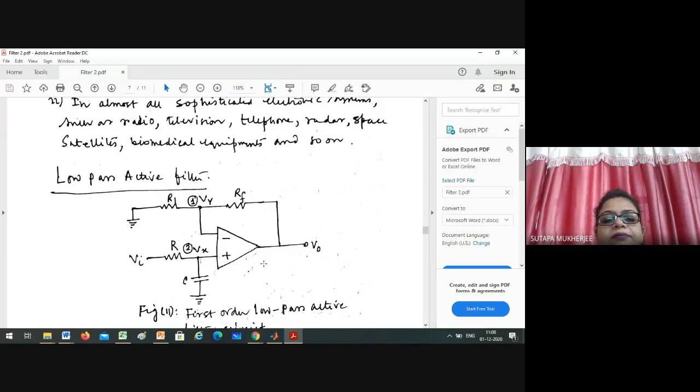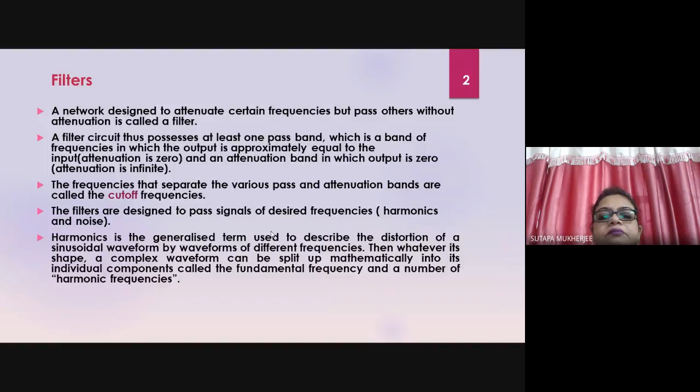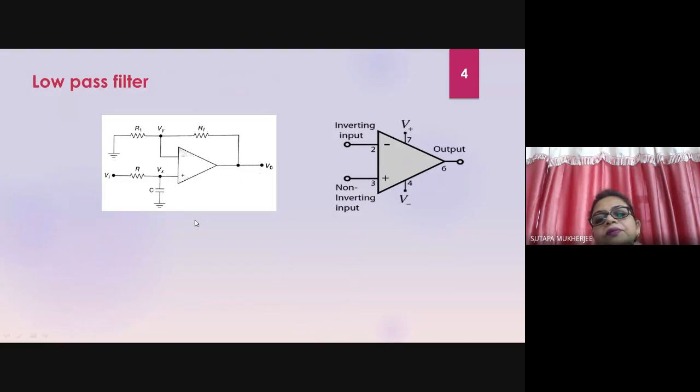Definitely I will explain. This is the figure. I'm sorry. Draw this figure. This is negative, I mean inverting input. This is R3, this is here, and this is the non-inverting terminal. I have applied the voltage input. Then what is your purpose? You have to show why it is called low pass filter. Initially you have to determine the gain. Gain means V0 by Vi.